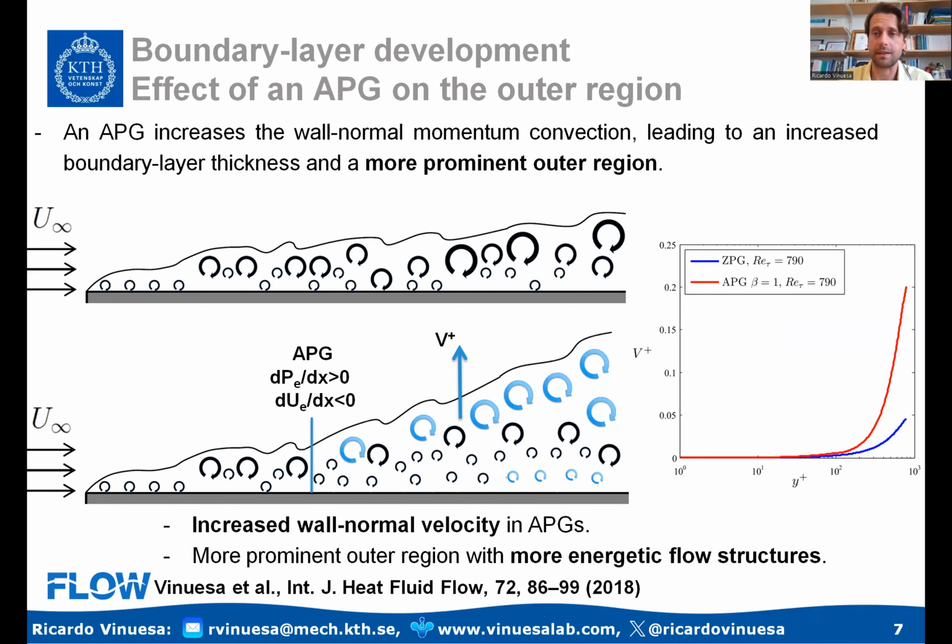and that's basically exposed to a quite strong average pressure gradient. At the top, you have a flat plate boundary layer where essentially as the streamwise distance increases, the boundary layer develops. And we have progressively a higher Reynolds number with more and more energetic motions in the outer region when there is a zero pressure gradient. So there is no acceleration or deceleration of the flow. So the free stream velocity is constant.